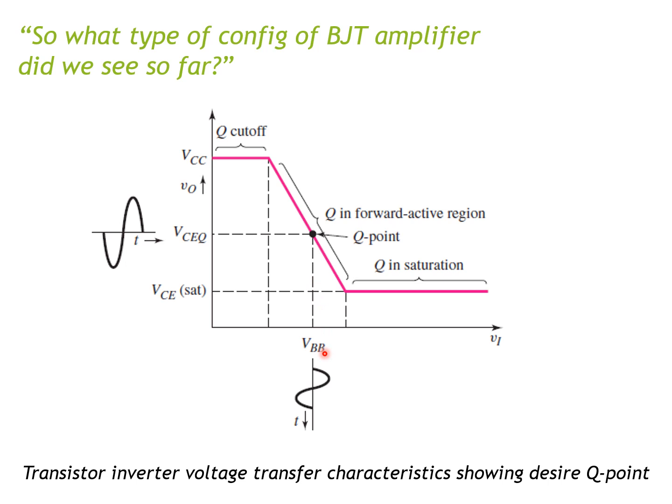If you do that, then you are able to appropriately use this circuit as an amplifier. Like previously discussed, if you over-bias it to this point, it's going to show some cutoff characteristic, or if you under-bias it at this point, you can see other cutoff characteristic. So what you want to do is figure out the appropriate Q point and bias your circuit properly.